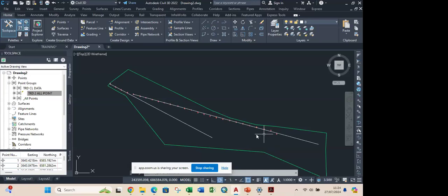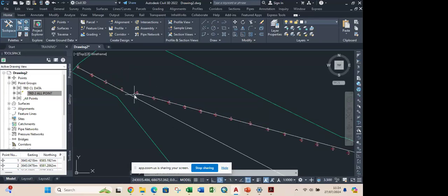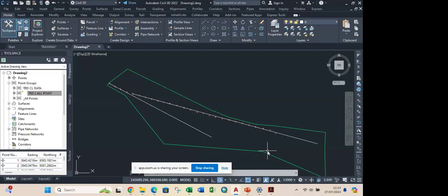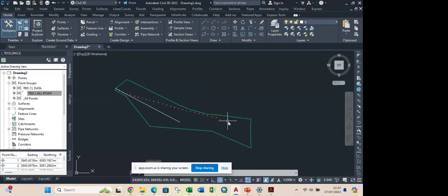So for me now, what I did, I pick my line and I draw straight, because when I go to survey on the site, I know that at this place, this is a straight alignment. But once the surveyor is picking this instrument and dropping the tripod stand on the road, they can't have a straight alignment because the point cannot go zigzag. But I know that's a straight tangent, being that there's no obstruction, it's a clear path. I'll just take it perfectly straight.